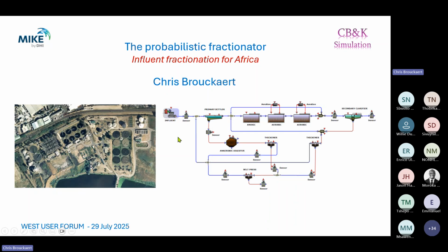And the other thing that is critical is the characterization of the influent. That's because everything that the plant does is dictated by the influent. Even the microorganisms that do the treatment are derived from the influent, and they adapt to its characteristics. So if you have the wrong characterization of the influent, you can't really expect to get good results.